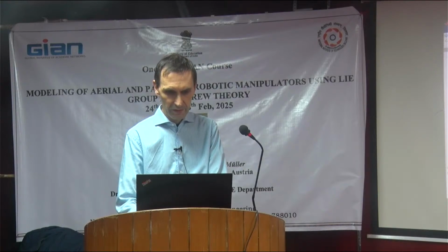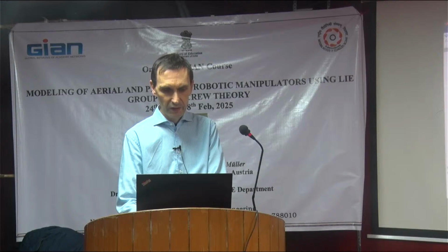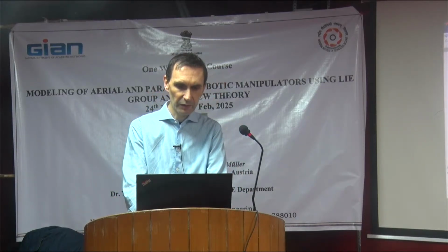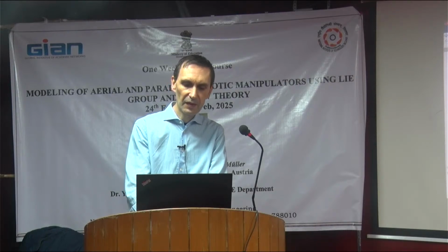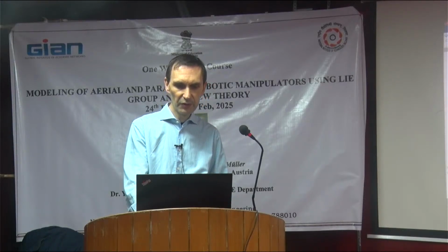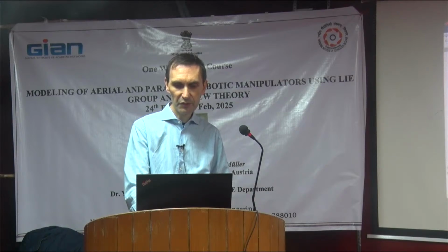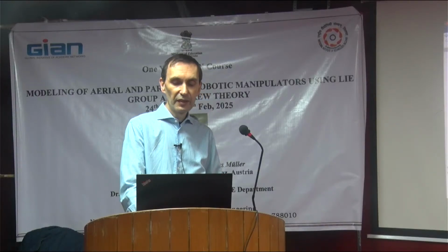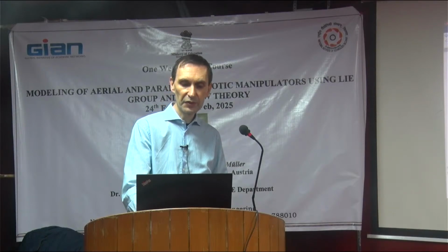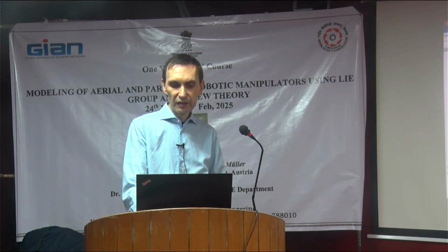So now we have this zero reference pose. The vector R is of course defined as I was saying. And then we get, what do we get? This is a function that constructs a homogeneous matrix out of the rotation matrices and the position vectors. And then eventually I can use the exponential formula to compute as we did before. Remember, this was the funny expression we got. Eventually we get the motion of the first frame, and this is the motion of the second frame due to the joint motion. And this is exactly as we had before.